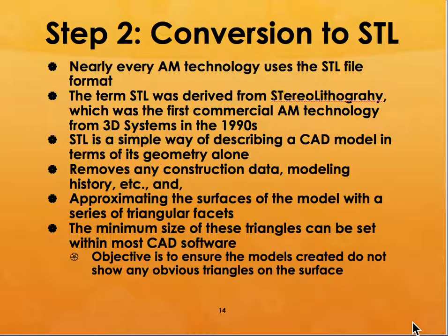It is just a way of describing a CAD model in terms of its geometry alone. And it removes any construction data, modeling history, etc. It approximates the surfaces of the model with a series of triangular facets. And the minimum size of these triangles can be set within most CAD software.